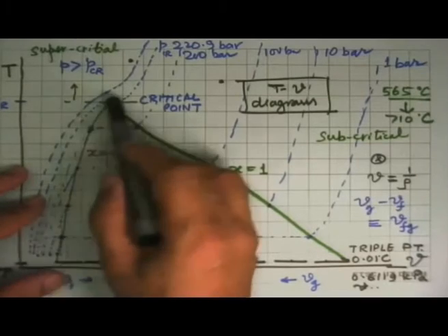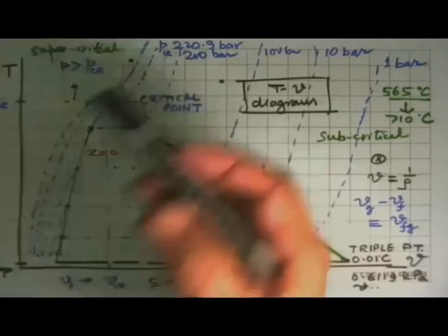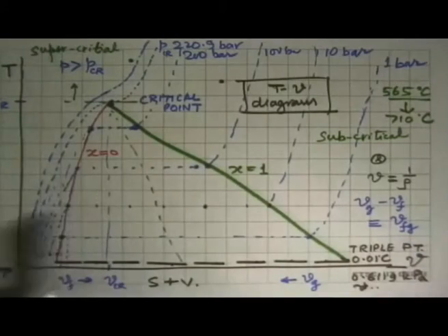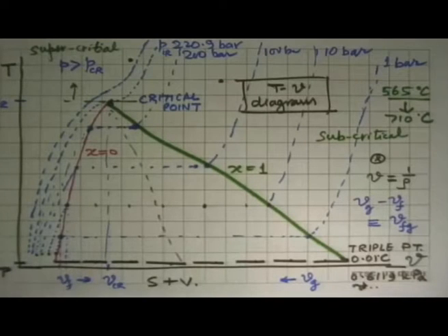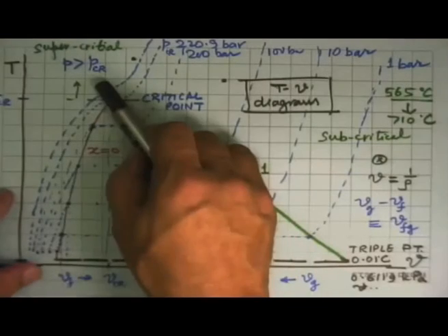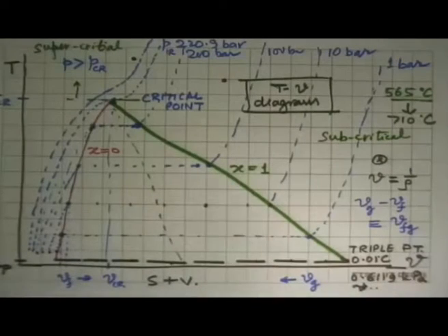It continuously shows a behavior of one type only, where the intermolecular spacing is now fairly tight and very close, and it doesn't show any ability to become a vapor by getting the molecules very far apart. So that's why this happens here. And of course, if pressures are more than the critical point pressure, there is absolutely no hope, because now you have compressed it so much, molecules are so close to one another, they have no chance to get away from each other.